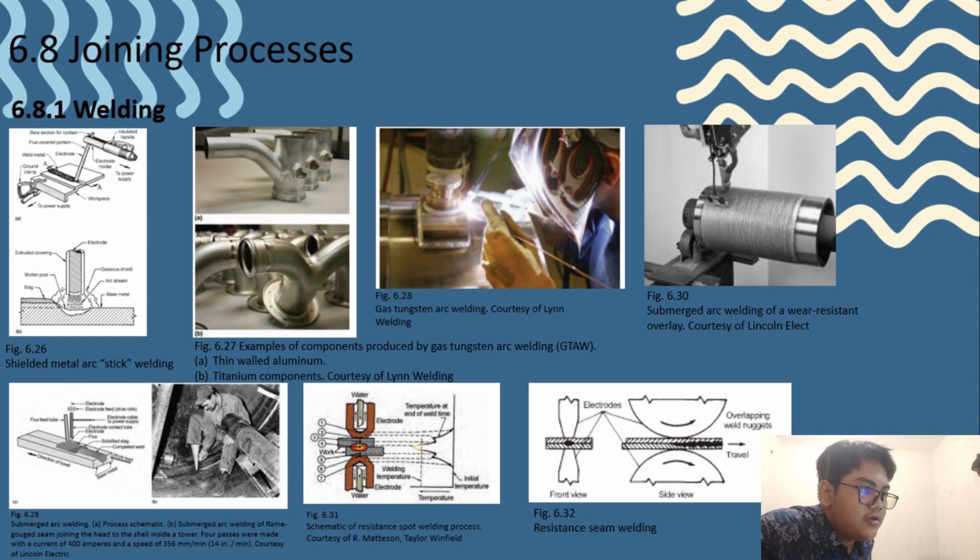Solid-state welding. Not all welding is done by fusion, with melting, intermixing, and solidification of the metals being joined. Atomic bonds can also be formed by solid-state welding, such that faying surfaces coalesce and bond at temperatures that can be below the melting point. The bonding process is based either on deformation or on diffusion and limited deformation, so that atomic movement creates new bonds between atoms of the two surfaces.